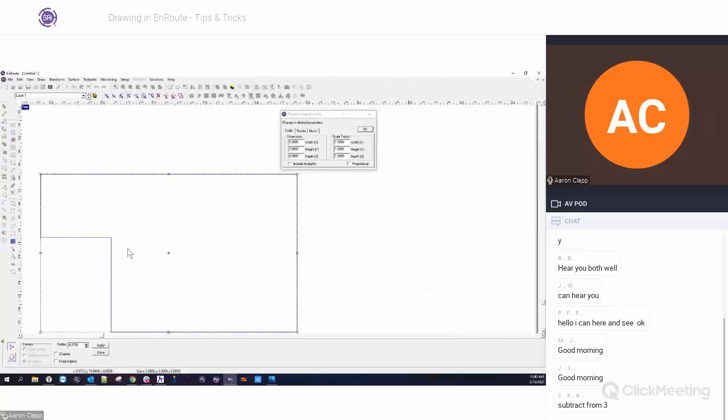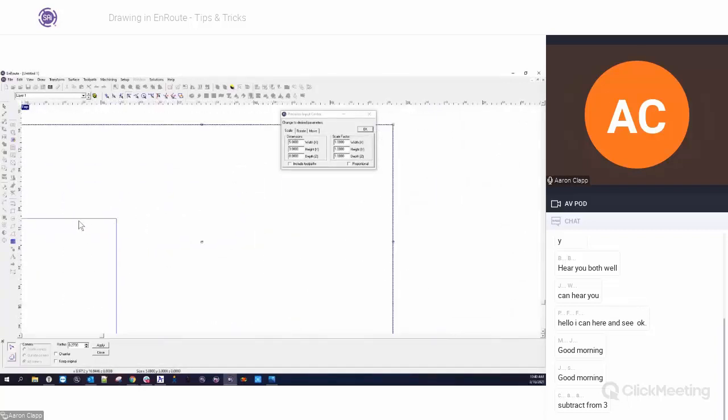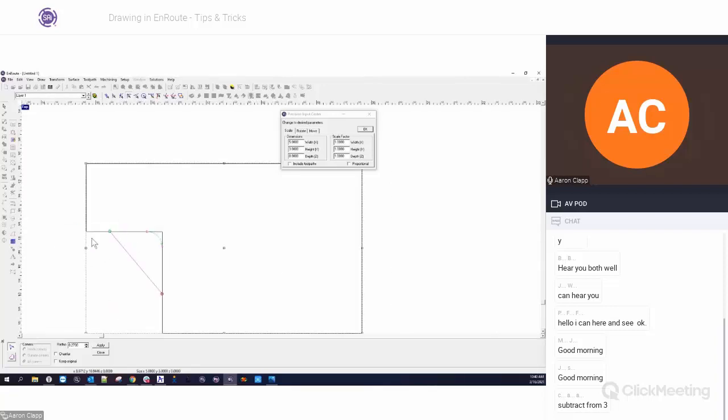The way that I'm going to do this is I'm going to zoom in and place a point on either side. So a little green circle there, a green circle here. I usually go way bigger than what I need, just so that I don't have to adjust it. But if you do need to adjust it, you can move these back and forth. If you end up having a radius that's larger than these two points, you probably have to drag them out like this in order to get the radius to fit right. So I've got my radius of 0.27 already set. Technically, I don't have to have these out here.